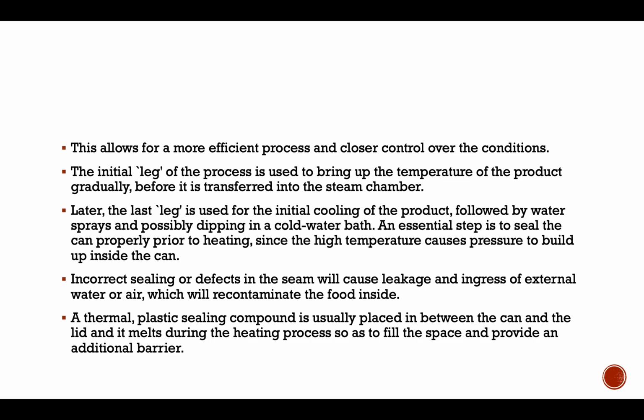The initial leg of the process is used to bring up the temperature of the product gradually before it is transferred into the steam chamber. Later, the last leg is used for the initial cooling of the product, followed by water spray and possibly dipping in a cold water bath.